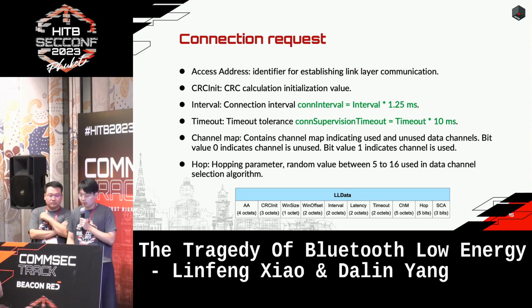And the LL data is the most important part in the connection package, which defines the physical characteristics of BLE communication. Among them, the access address is used as an identifier for establishing link layer communication, and the CRC init value is used for subsequent CRC calculation. The interval is the connection interval, and we know BLE hops frequency, and the actual frequency is not fixed.